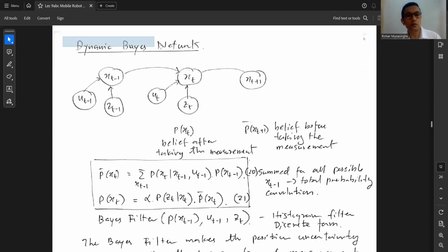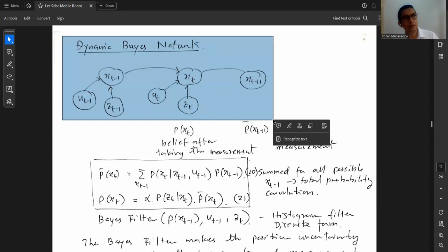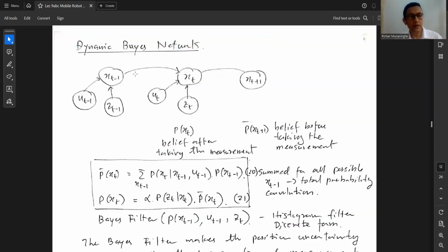Now, we need to understand what we are dealing with here. I want you to recall your memory on the state space model. State space model is actually a dynamic model, you can say a vehicle model here. When you know your previous state, you can calculate your present state if you know the control signal that is coming in, control variables, one or two or many. So when you write down these equations, you have the state space model eventually. And in the state space model, there is observation, measurement also. Remember the second equation, y equals Cx, the output equation. So that is the measurement. So these are all connected together.